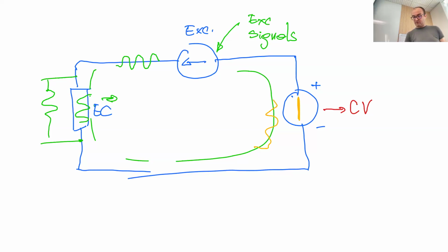And because it is in constant voltage mode, it has high frequency bandwidth, it is capable of reacting without changing the current. And these voltage changes will affect only our excitation unit. And our excitation unit is designed in such a way that it has a bandwidth of more than 100 kilohertz. So it is capable of reacting.